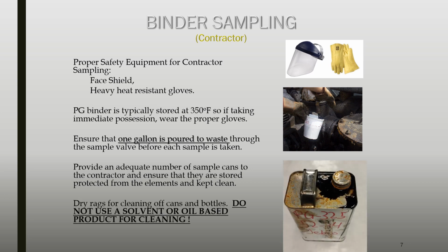Only dry rags can be used for cleaning off cans and bottles. Do not use a solvent or oil-based product for cleaning. This can contaminate the sample.